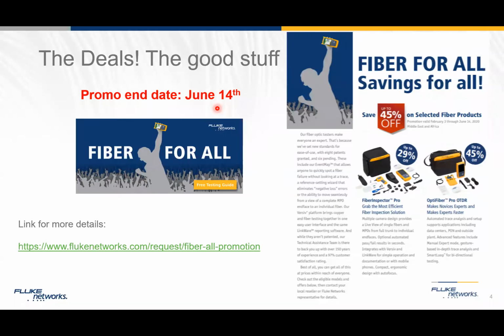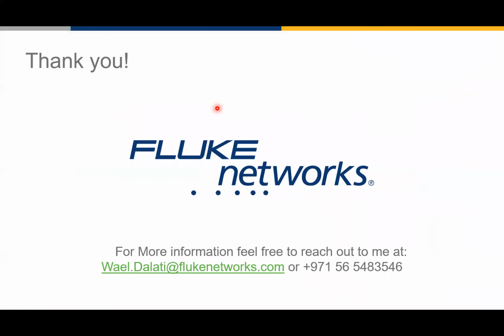Now, in the outside plant world, where we use single mode, you may come across a large splitter, 16 or 32 port, or you may have a fiber that is more than 100 kilometers long. In that situation, you may use a longer pulse, and you want the entire pulse to fit into the launch fiber. Now, if you are using shorter single mode lengths, the 160 meter launch fiber that we include is going to work just fine up to a pulse width of 1,000 nanoseconds. And that is going to cover almost every common point-to-point link in a campus environment, in a data center environment. But when you start going to things like splitters on the fiber or longer lengths of fiber, then you may need to use a longer fiber.